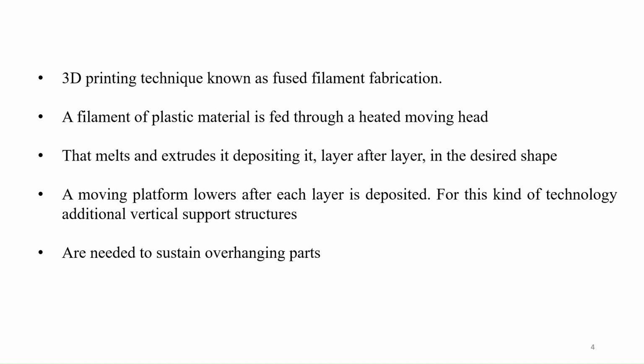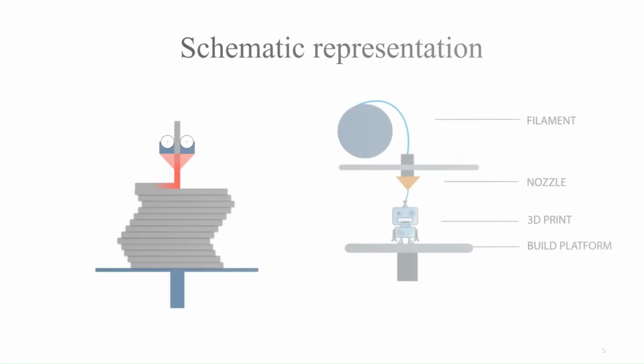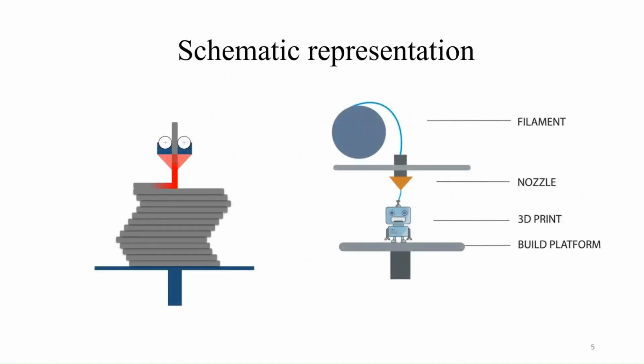The advantage of 3D printing is the ability to produce very complex geometric shapes that would otherwise be impossible to construct by hand, including hollow parts or parts with internal truss structures to reduce weight. Fused deposition modeling, which uses a continuous filament of thermoplastic material, is the most common 3D printing process used in the 2020s, known as fused filament fabrication.